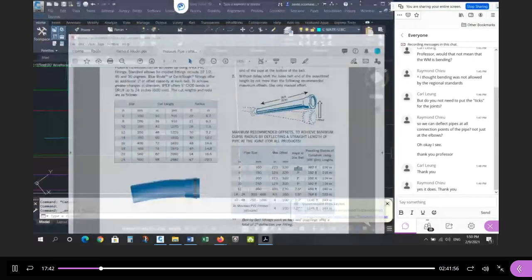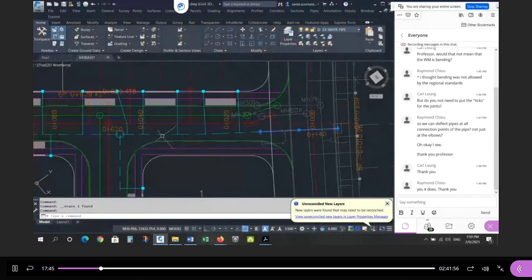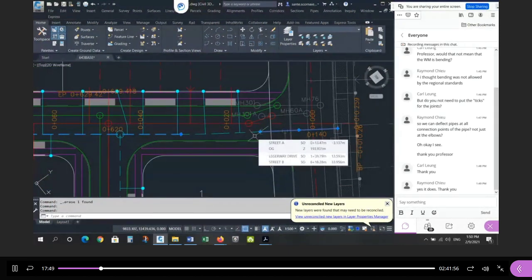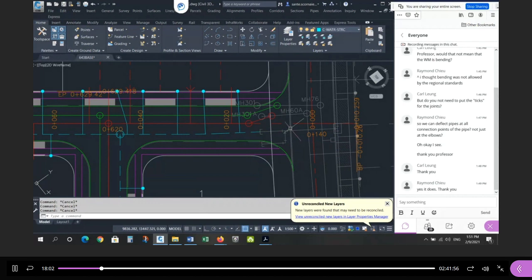So the method here really is this bearing and this bearing are so close to each other that the best solution is to bend the pipe using joint deflection and not by any kind of fixture, a 22 and a half, 11 and a quarter, and so on. Okay, it's so close to straight that we can just bend the pipe using joint deflection. So anybody that used an elbow of any kind here, it's not going to work. I didn't take marks off. As long as you made the connection, you did something, right? The plumbing works, but it's not practical.